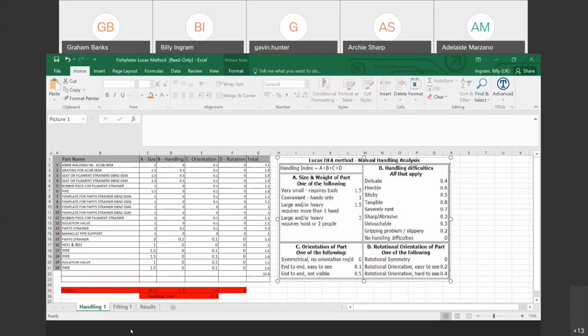Sorry, what's the story with the isolation valve? It's just that the isolation valve is shown on the image we've got. It's hand actuated, so it's quite a small valve. But when Gavin spoke to the guys concerning the stress, they said it can come with a different actuating method, which might be either air driven or electrical, which makes it a bigger, bulkier item, which can then act as a pendulum. That's the reason behind the beefing up of the design on the second fish plate. Interesting.